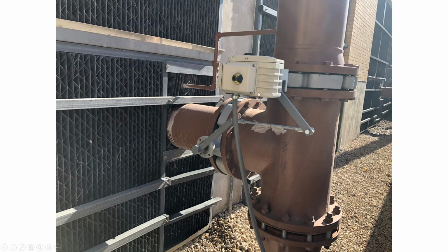This device is the actuator that's getting its signal from the building automation system that tells it what position to be in. And then you can see it's mechanically linked to the valve in this other pipe that's bypassing the tower. So this actuator is getting a signal to tell the water whether to go to the top of the tower or actually bypass the tower, and that is contingent on often outside air temperature so that they don't freeze the tower. So already we can see that instrumentation is informing control devices.